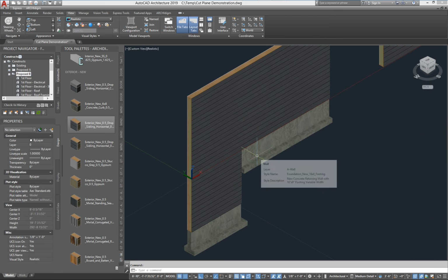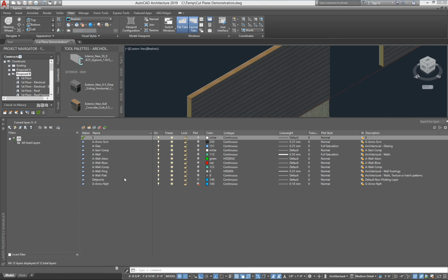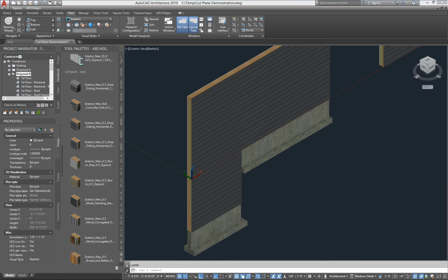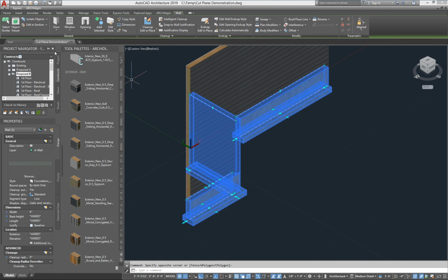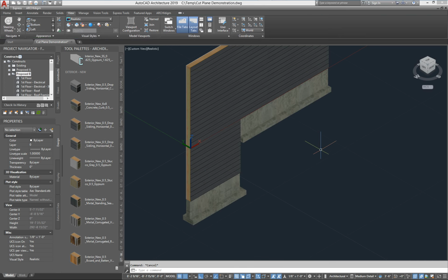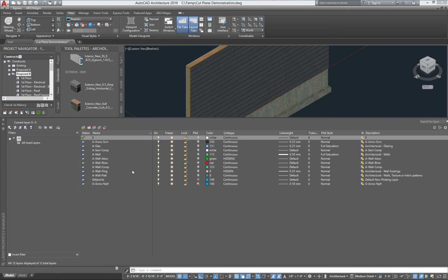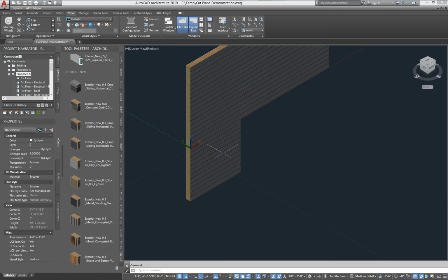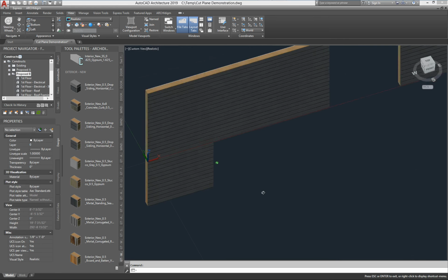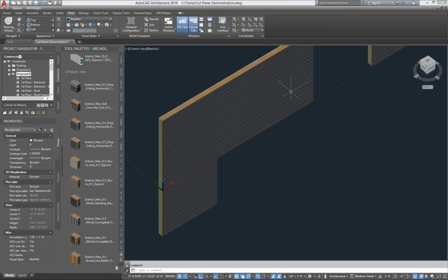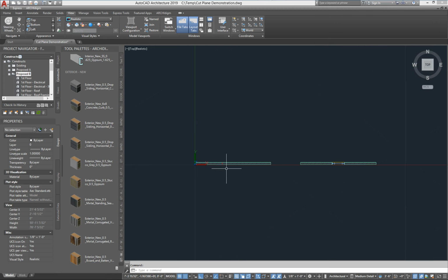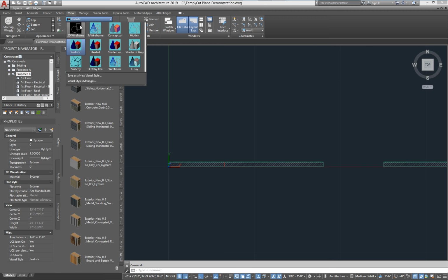I am going to go ahead and go to layer. First off, I'm going to take those walls and stick them on a different layer, footing, and then I'll go ahead and just freeze that layer. Boom. We'll get this out. Okay. I don't need those in the way of this demonstration. So just so we're aware, this is a wall that now goes down below the 0 and definitely below the global cut plane. We'll do a top view. All right, go back to 2D wireframe.